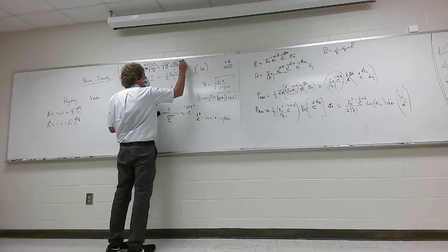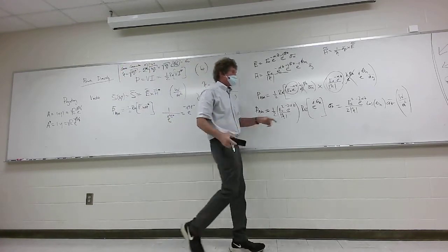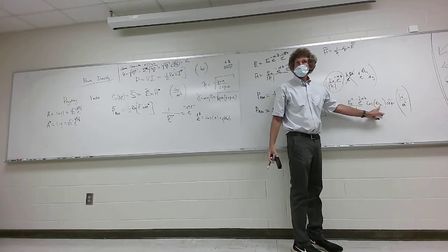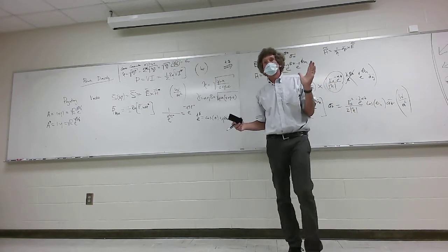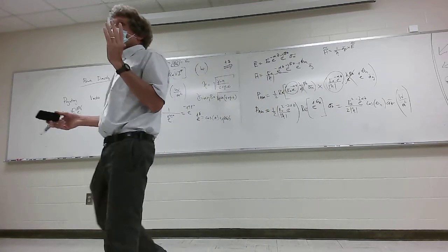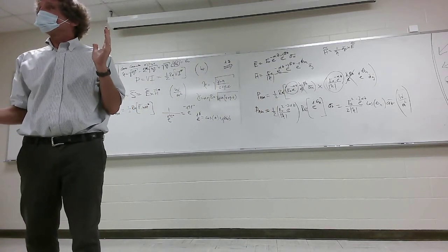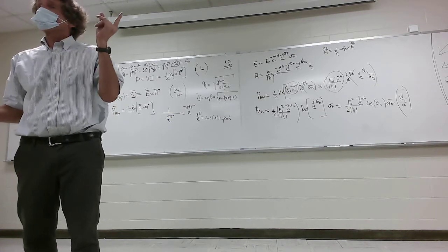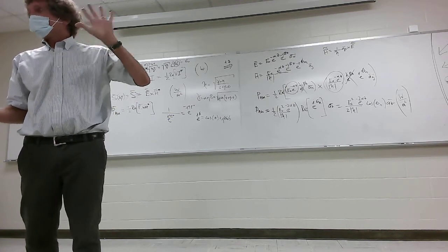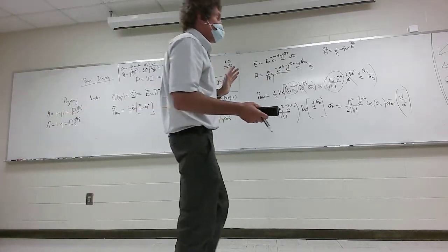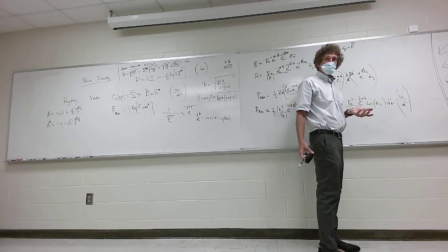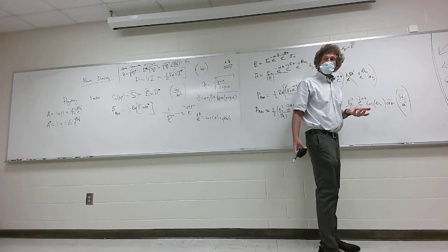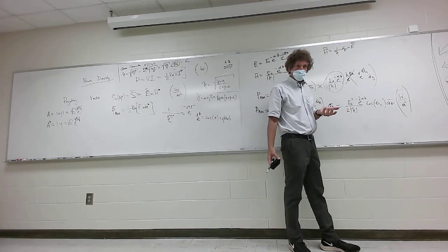This would be theta sub eta that would go in here. So the cosine of 45 degrees would be 1 over the square root of 2, wouldn't it? Go with me? Now here's the thing. Usually, the closer you get to a lossless region, the closer the cosine of that angle goes to 1. As a matter of fact, usually it is 1. Y'all follow me? Like in the atmosphere right here. But when you get into good conductors or better conductors, it can go all the way down to 1 over the square root of 2. That's my point. Got it? And that would be the worst case if it was a very good conductor. You follow me on that, class? That would be power flow.